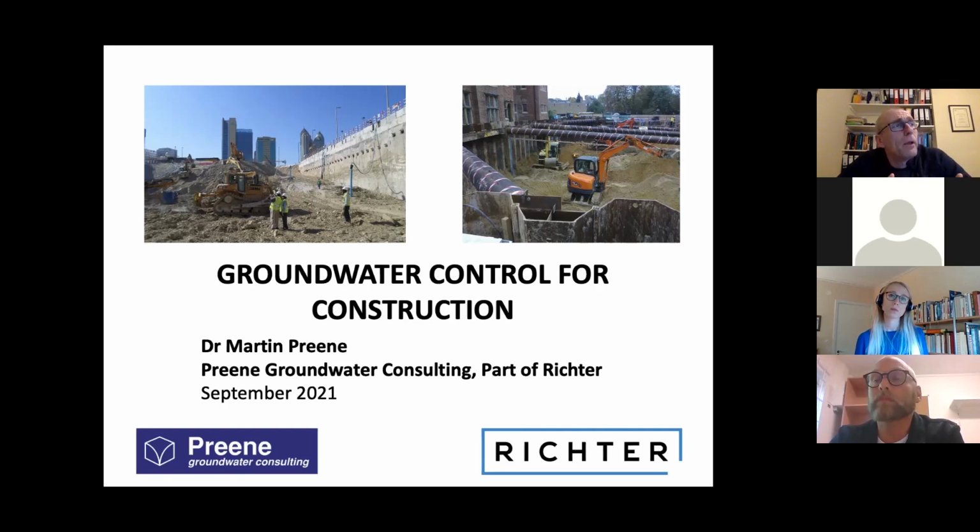Like all the things, a term I use is I view these methods as a toolkit. If we're trying to control groundwater, we start with a toolkit of methods, which includes the exclusion methods, the pumping methods, and the counter pressure methods. And the challenge for designers and contractors is to make the best use of that toolkit. And cost is a factor, time is a factor, and risk is a factor. And I think ground freezing probably comes along when you are in a very risky scenario and it needs to work and you can't pump. Then ground freezing might be expensive, but it can be the best solution considering all these factors.